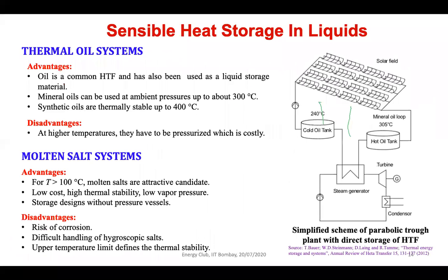Next one is, we can move from water to oil. So oil as heat transfer fluid has not been tested much. So people now are trying to develop oil as heat transfer fluid instead of water. But basically, the operation range of oil-based thermal energy storage depends on the flash point of the oil.